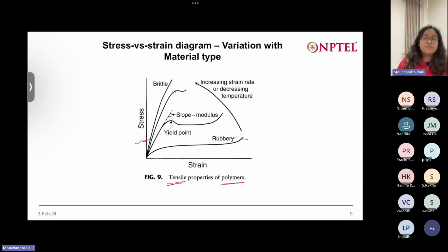And if you were given some kind of stress and strain plot and asked, by common sense, for which type of biomaterial class would you say this stress and strain diagram belongs, I think you guys will be able to interpret by looking at where the yield point is, how much longer the elastic region is, how much longer the plastic region is, and at what point it fractures.